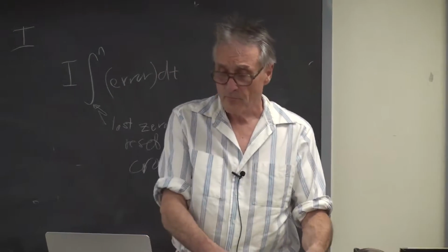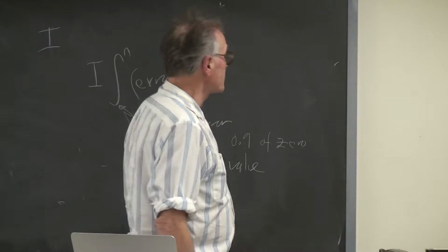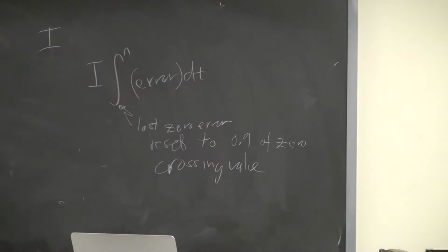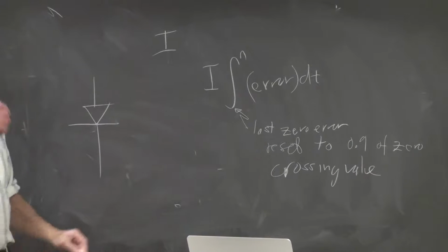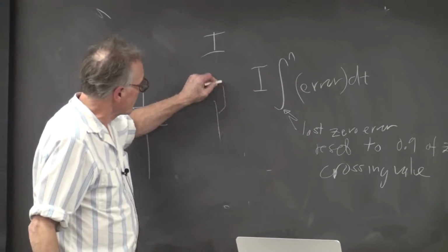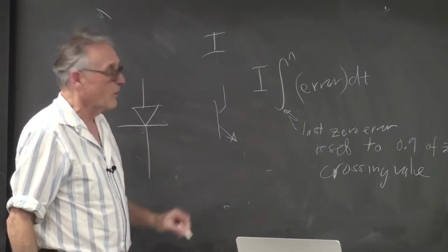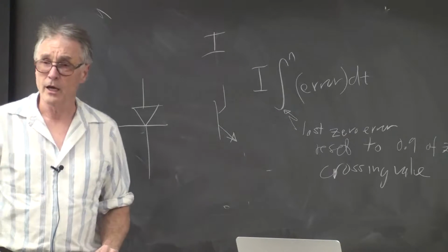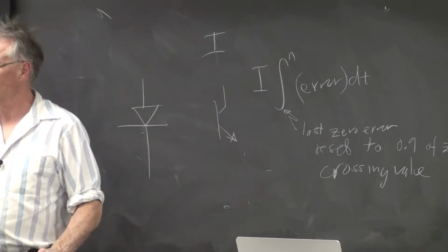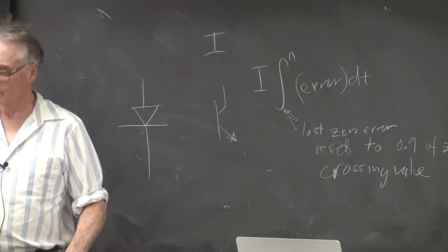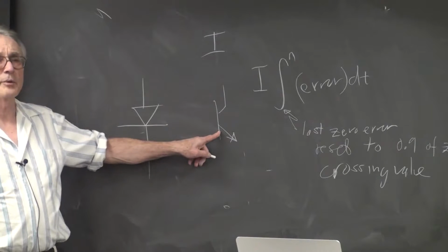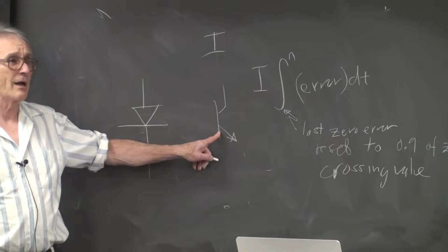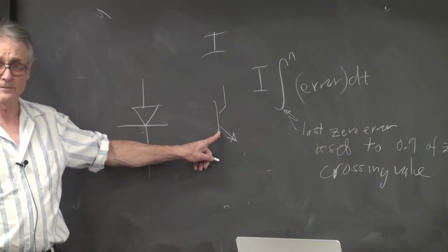The sensor circuit consists of a light-emitting diode. The light-emitting diodes and the phototransistors are in one drawer marked IR. And you can tell them apart because the transistors appear black to the human eye because they only pass infrared.